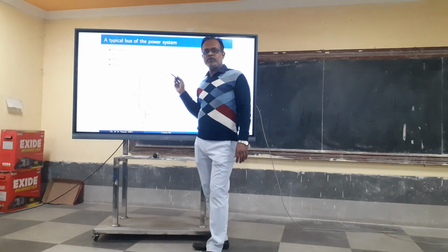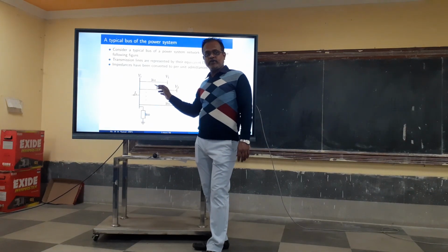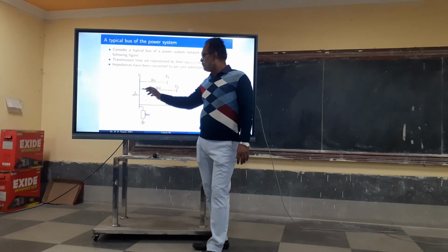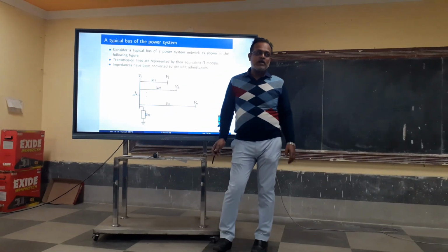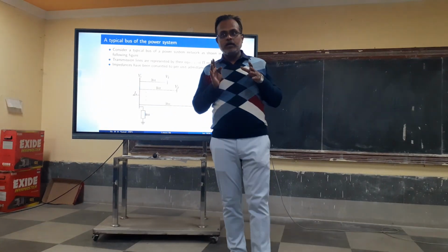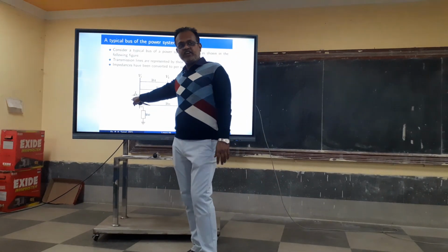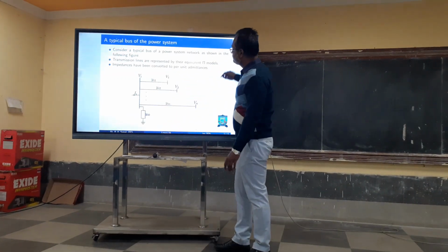What is the equation? The KCL equation? Vi minus V1 into Yi1. Vi minus V2 into Yi2. So all this summation is the total current that is coming out from the bus, and hence is equal to the injected current. Injected current may be because of a generator. Okay.